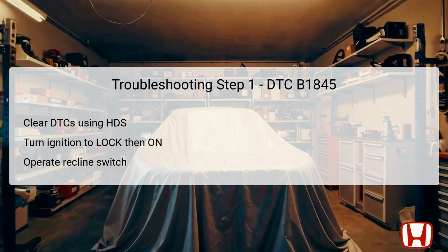Once the ignition is set to on, operate the recline switch in both directions for more than 1 second. This action aims to simulate usage and check for any immediate response from the system, which is essential to diagnose the current state of the recline switch circuit effectively.